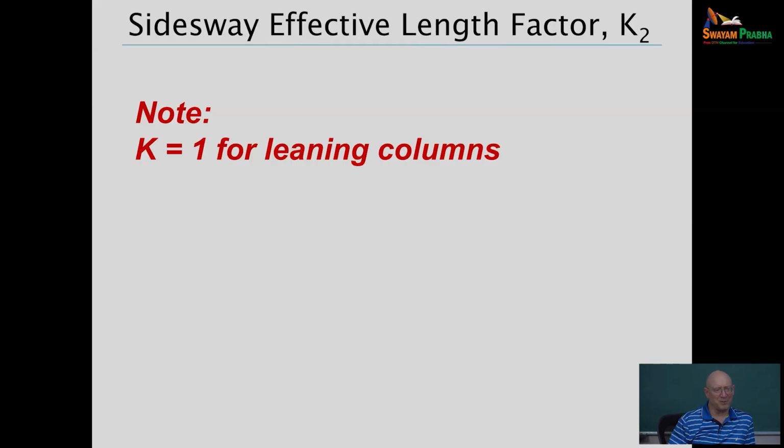Now you get into something that in the literature is referred to as the effective length factor paradox, where it's really not so appropriate to use this really large K factor for something like that because it's not really helping the story. You're just penalizing the column.